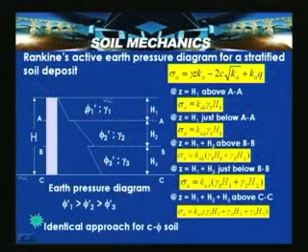Here what we need to consider is that just above AA and just below BB, you try to get these ordinates. When you obtain the resultant pressure, that gives the resultant earth pressure, that means the resultant of this particular saw-type diagram, which is nothing but the earth pressure diagram in the case of a stratified soil. This ordinate movement to this side and that side depends upon the properties of the soil, for example if phi 1 is less than phi 2, so based on that it changes.